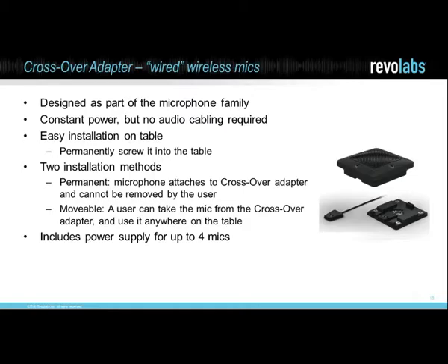Does this help me set up a conference facility where I don't have to cable the microphones and I can move it around? Yes, for example, I've seen training rooms where the tables are always in a reconfigurable situation. They may be in a horseshoe arrangement for a meeting one day, or they'll be in a tiered training arrangement another day. And they incorporated one directional microphone for each three-person table that was permanently mounted, and when they plugged the table in to give them USB power and power for their laptop from the pop-up on the table, the microphone was activated as well. So it just became another component on the table that got moved around when they arranged the room.